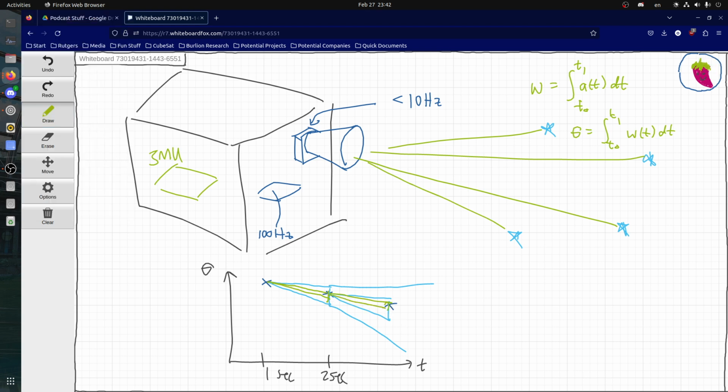So yeah, that's IMUs. IMUs run very fast. You can run them at like 100 hertz, and it'll mostly work. Not that you should, but you could. I know the faster you want to run it, the more error there's going to be, so you have to be more careful with the algorithms that you use, or rather, you have to spend time tuning it to account for the error.